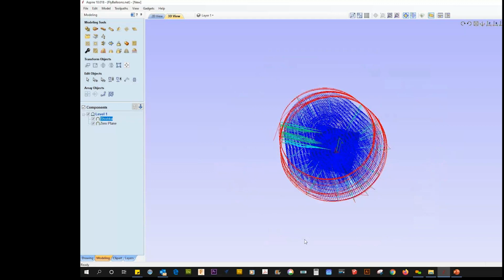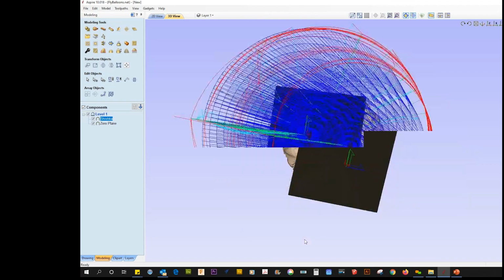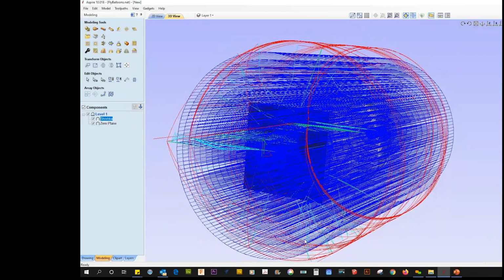And do you have a cutting side all the way up the cutting surface? It looks like it might be 1.5 inches or 2 inches. And a lot of those bits are only 2.5 inches long, and it leads to a fair amount of stick out, which alters your feed and speed, etc.